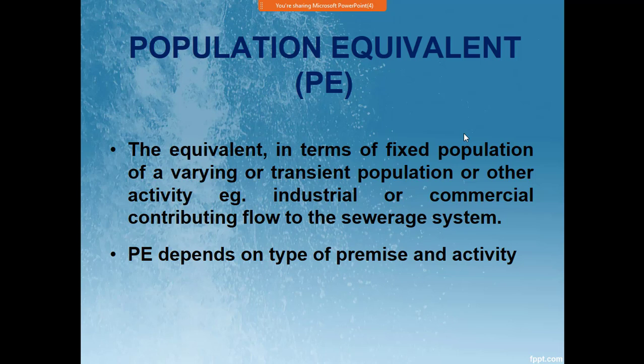Same at a hospital. At a hospital we have beds. One hospital's capacity can be 100 beds, 200 beds, 500 beds. For each bed there is drinking water, bathrooms, showers, cooking, cleaning, so many things that need water. So all of this is counted on the number of beds.